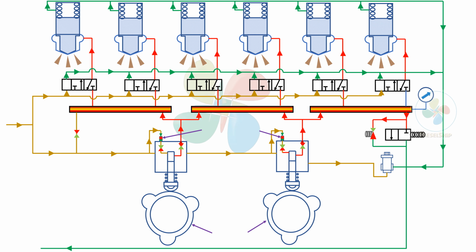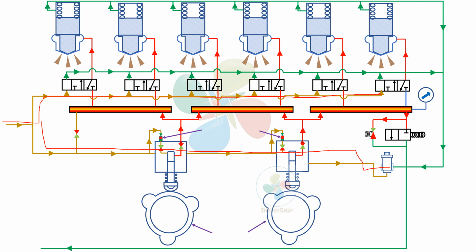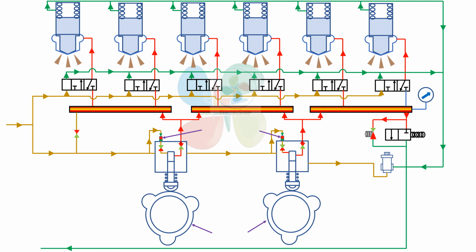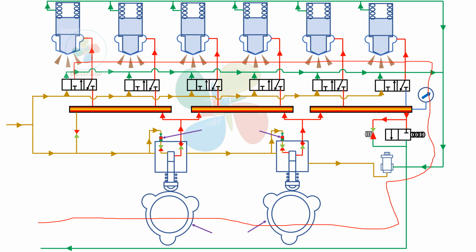Okay. The brown line or the yellow line that you see here is the fuel inlet line. This fuel comes from the fuel booster pump from the fuel skid. It comes at 12 to 15 bar depending on the engine size and the configuration, right? And the green line you see here is the line that goes back from the engine to the fuel system. It basically goes back to a buffer tank or a mixing column, whatever we call it in your ship. That's how it goes back, right?